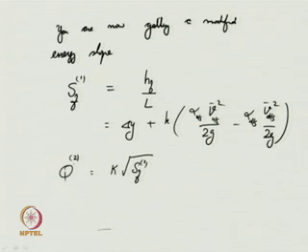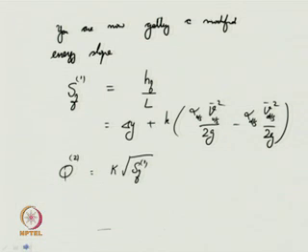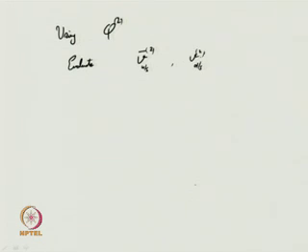Once you get this second approximation for discharge, again go back. Using now Q2, evaluate V upstream, which you can give as V upstream 2, and V downstream 2, and evaluate S2 now.